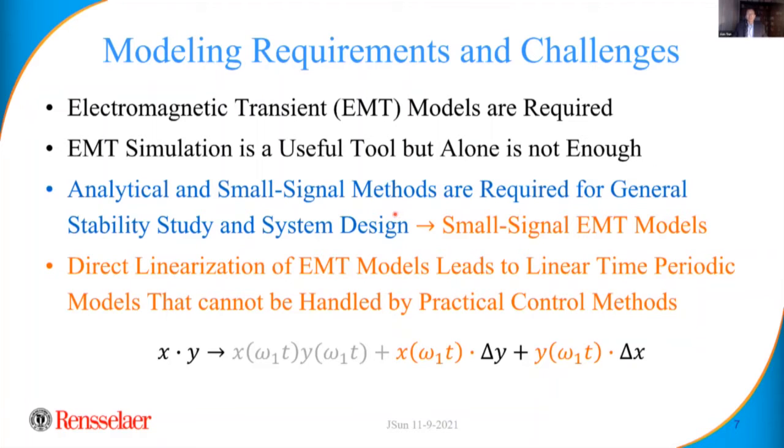So to do that, we need to work with small signal EMT models. Why small signal? Because every converter model, if you look at the time domain model, is nonlinear. So in order to perform frequency domain analysis, we have to linearize it. In other words, we need small signal EMT models.